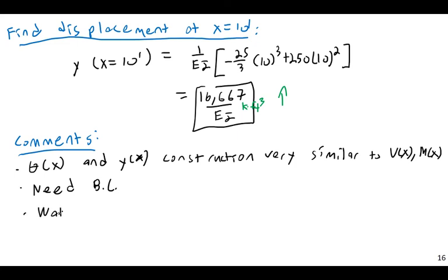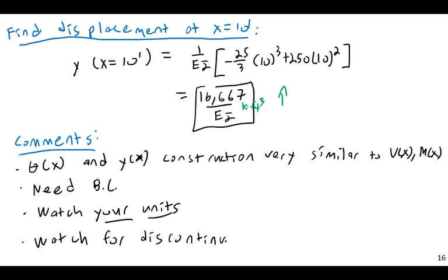Watch your units. You can do everything in kips, or you can do everything in pounds, you can do everything in inches, or you can do everything in feet, but you don't want to mix up inches and feet. This is very easy to screw up. Watch your units. And again, watch for discontinuities. Abrupt changes in load or support, either one represents a discontinuity.